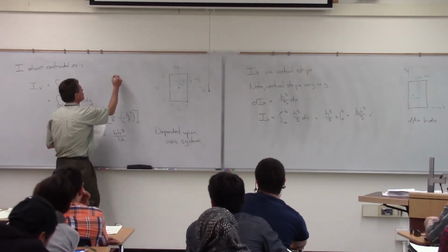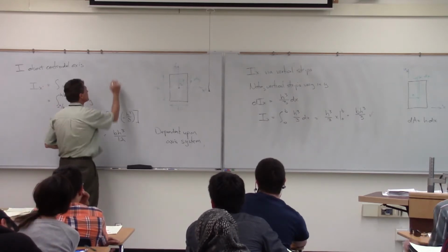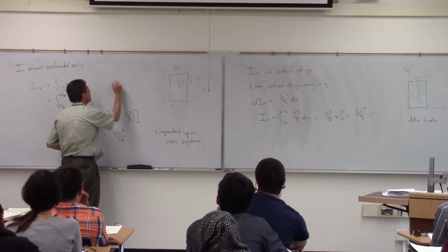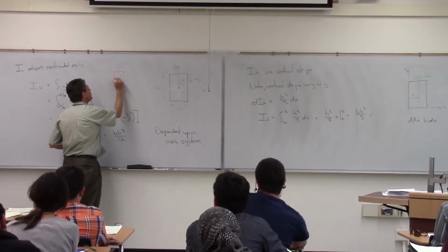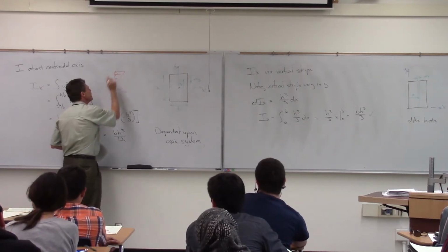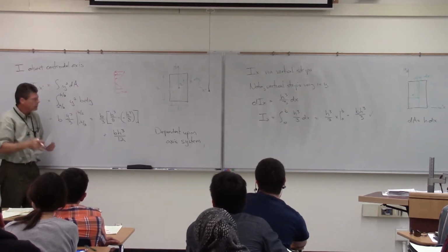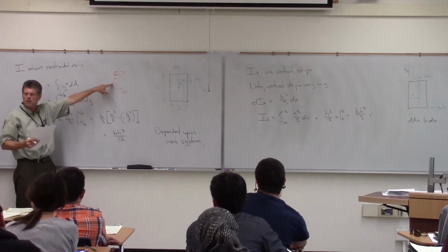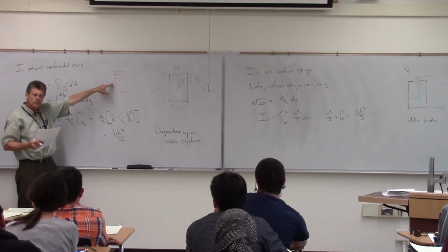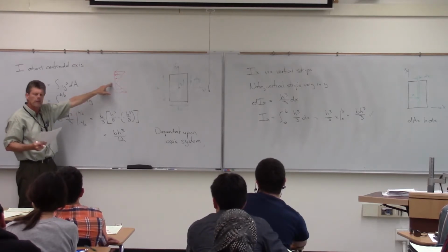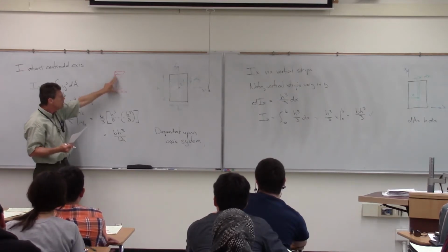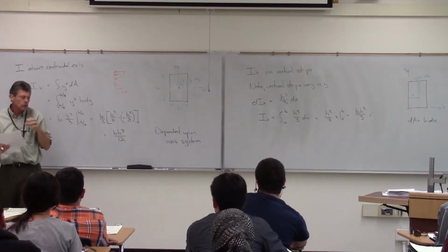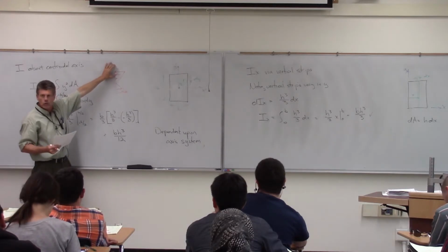And that's also based upon that distribution when we thought about the distribution of stresses. They look like this in a bending situation, and you'll see that there isn't really much going on there. So that's the concept behind an eye section there. There is shear and stuff we have to worry about, so that's a whole other force that we have to worry about. But in terms of the bending stresses and stuff, most of the action's going on out here.